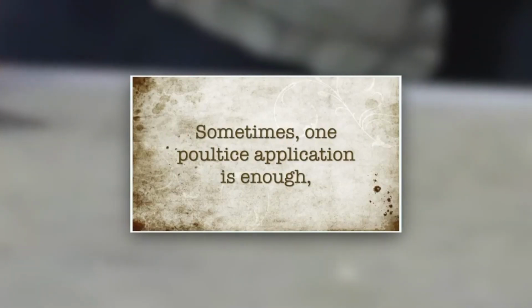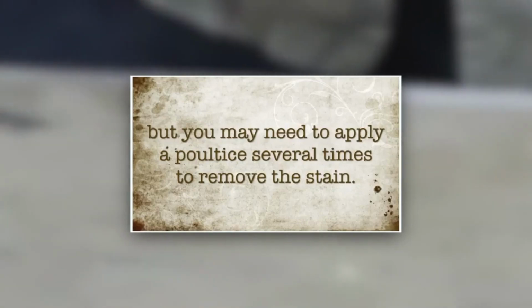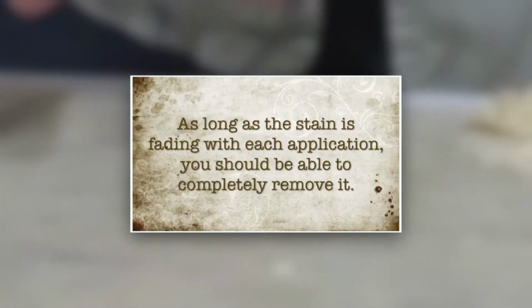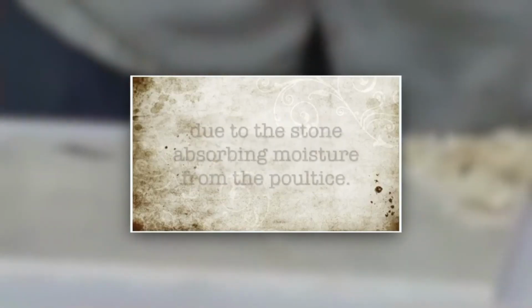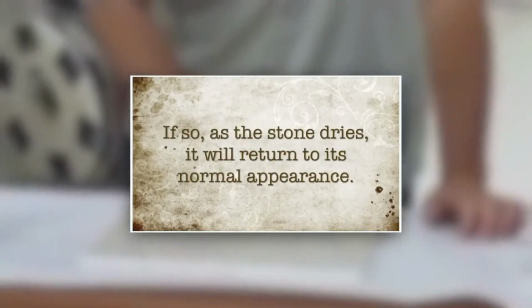Sometimes one poultice application is enough, but you may need to apply a poultice several times to remove the stain, especially if the stain is oil-based. As long as the stain is fading with each application, you should be able to completely remove it. Also note, the stone may appear darker where the poultice has been applied, due to the stone absorbing moisture from the poultice. If so, as the stone dries, it will return to its normal appearance. The final step is to clean up the dry poultice residue. Use a pH-neutral, stone-safe cleaner to spray the area and wipe it down. It's as simple as that.